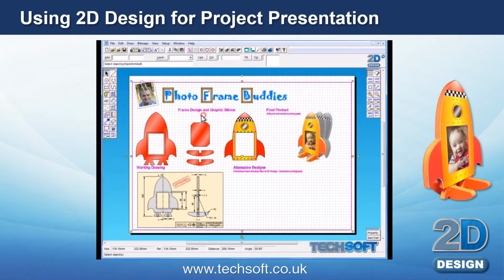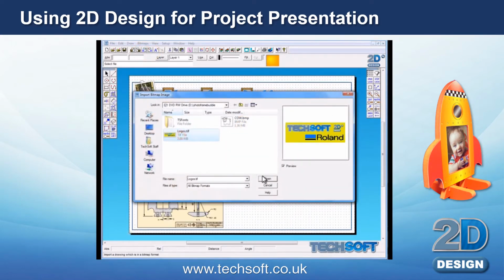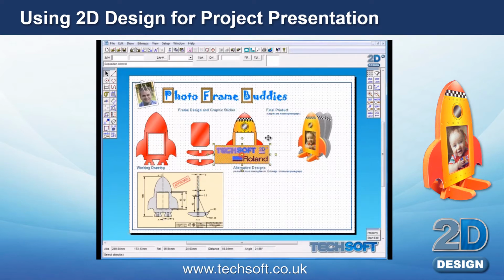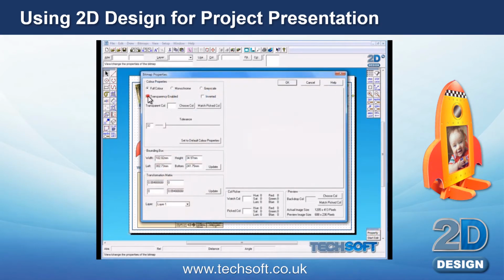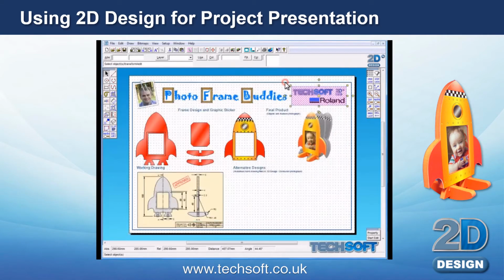We will now add a logo. Choose Import Bitmap. Change the DPI to 300 and OK. Move the logo over to the top right corner. With the bitmap still selected, click on Properties. Now we want to set the yellow to transparent, as you can see here, and OK.